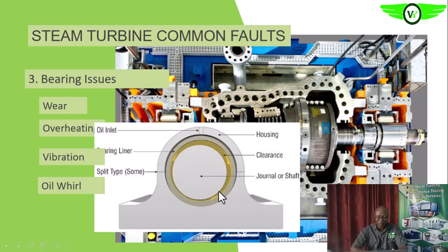So this thin film of oil can actually cause whirl, maybe if we have excessive clearance or the weight of the rotor is not enough. You see that the tendency of this oil, as it is pressurized, of throwing this shaft of the rotor away from it, are you getting it, will increase, and that can cause whirling, excessive vibration, and that irregular rotating movement of the rotor.